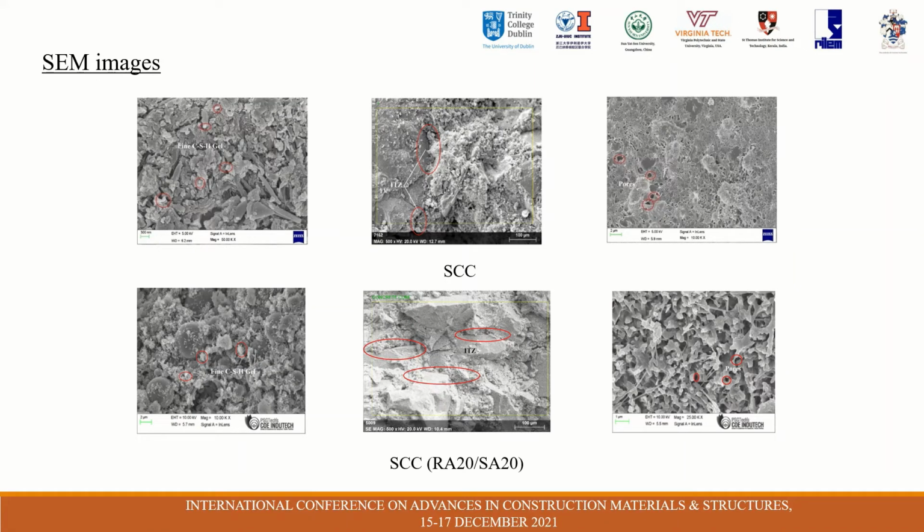From the mechanical tests, the optimum sample and the SCC reference mix are taken for the physiochemical characterization and microscopic observations. At first, the SEM analysis is carried out to study the amount of fine CSH present in the material, the interfacial transition zone, that is the bond between the mortar and the aggregate, and the amount of pores present in the material, which is analyzed under different magnifications and compared with the reference mix.